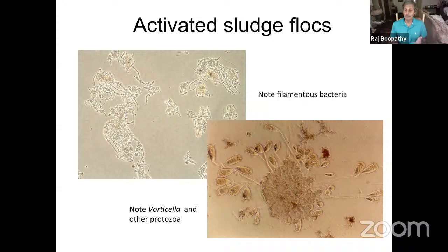And then you're going to have a filamentous bacterial growth, and we call that bulking. Okay, the bacterium responsible is called Sphaerotilus natans. It's a filamentous bacterium. It starts to float, and instead of settling, the whole waste is going to float in your wastewater. So we have some problems to address on how to control this bacterial system in the flock.